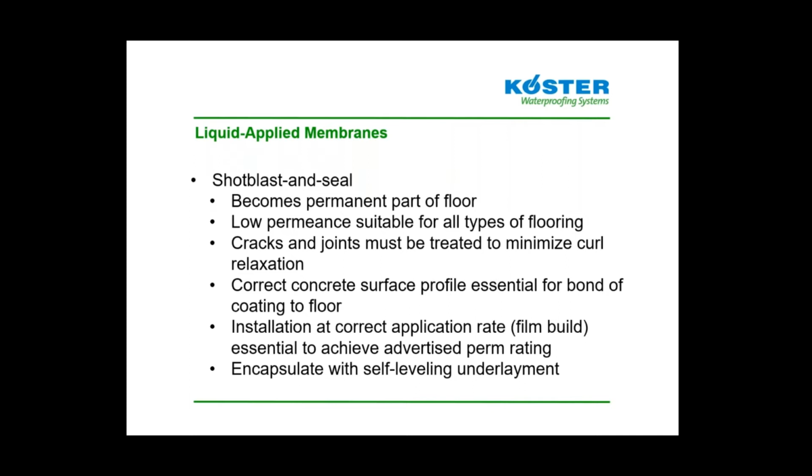Obviously, quality control during the installation is very critical to performance. Concrete must be correctly profiled, clean, and liquid applied membrane must be applied at the correct application rate. If underlayment is installed, obviously care must be taken to follow the installation procedures of those products as well, mixing and applying carefully to avoid any kind of issue with the underlayment product. After the entire system is installed, it'll result in a hard, flat, smooth surface, ideal for any kind of floor covering installation.